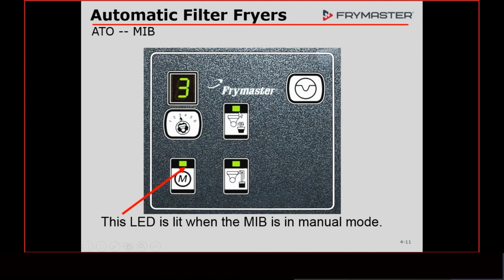When it's all the way open, the resistance value that it sends back tells it that it's in the open position, so it indicates that by the light staying on. When it's in travel, the resistance is moving and not stable, so it's going to flash because it doesn't know what's going on. It can just assume that the actuator is traveling. That's why it's not locked into any one resistance.